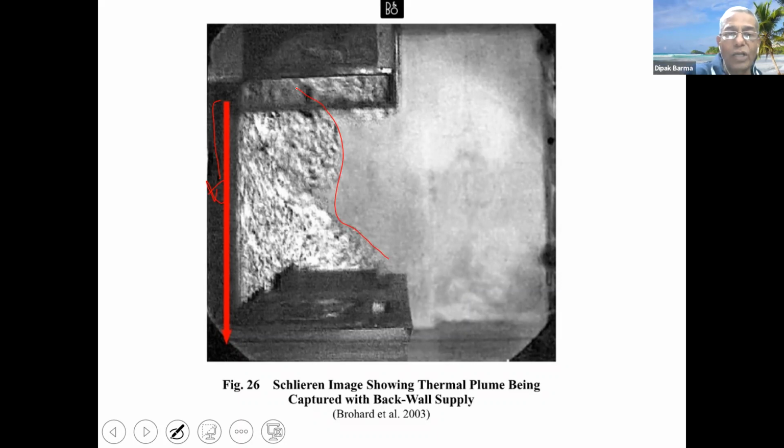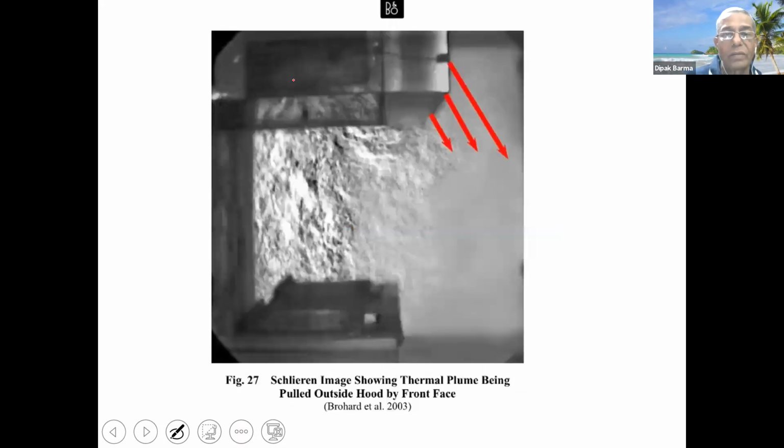Because of the Coanda effect, which I was talking about earlier, this airflow continuously downwards is having a great impact on improving the flow of the plume into the hood. Throwing it outside to the side at an angle is also allowing the smoke to be pulled out.